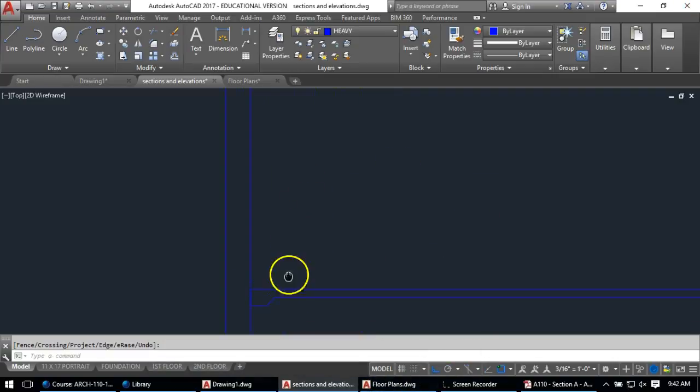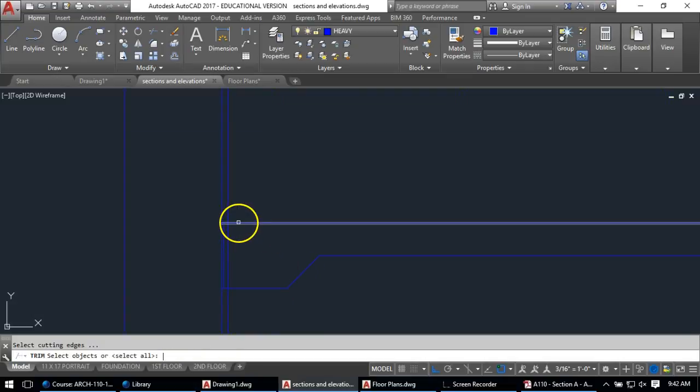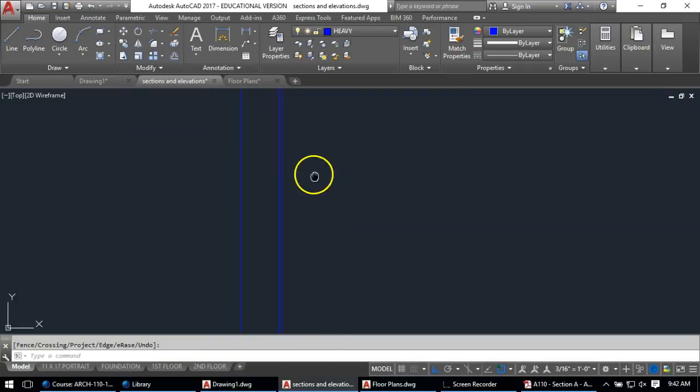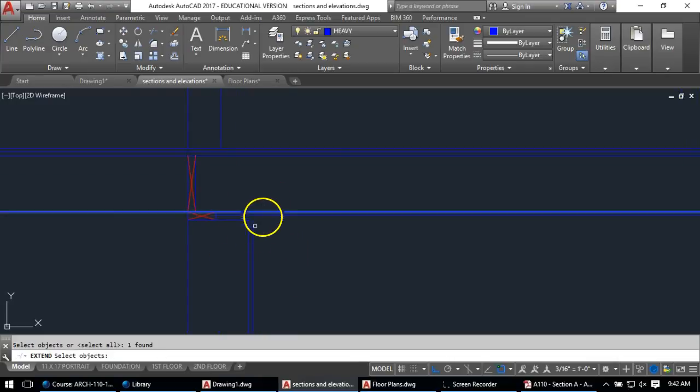I'll do that. And it'll come up, we'll notice that there is a couple vertical lines here. So there's an interior drywall sort of partition. There's a furring strip. A furring strip is basically a skinny piece of material that can hold drywall against a concrete wall or a brick wall, whatever the case might be. And I think it's 3/4 inch. So I'm going to offset 3/4 inch. There's different sizes of furring, but I believe the note says 3/4 inch. Of course, trim it up to this location, and it's going to go up to basically the joist height.